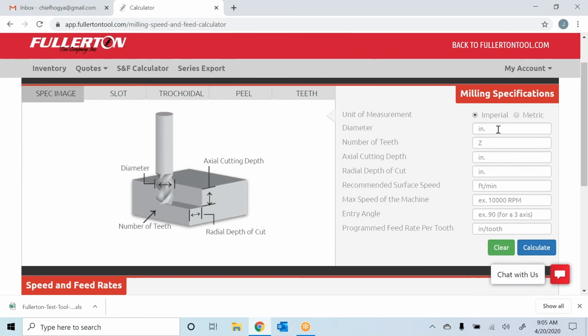When you start looking at high efficiency machining, we know that anything less than 50%, so 49% and less, there's chip thinning that occurs in milling. Anything more than 50%, it's just 1-to-1. So if you're looking for a 3/1000 chip load, 3/1000 is what you're going to get if it's 50% or more of the end mill. But less than that, you're going to get chip thinning. So to do that, you need a calculator to figure out how fast you should run so you get the proper tool life on the tool.